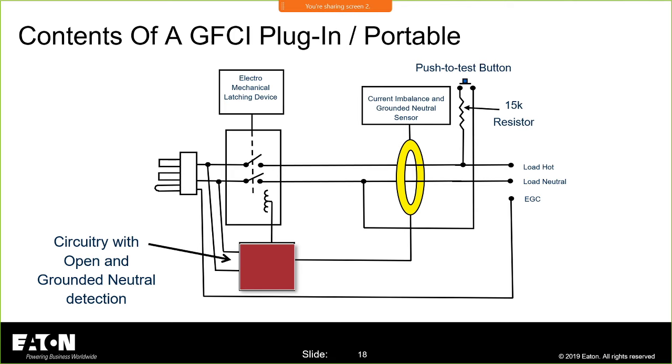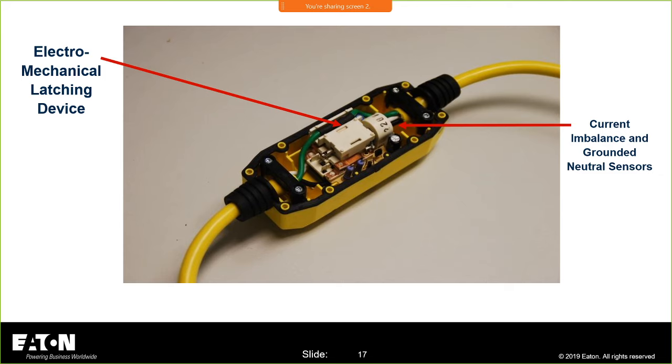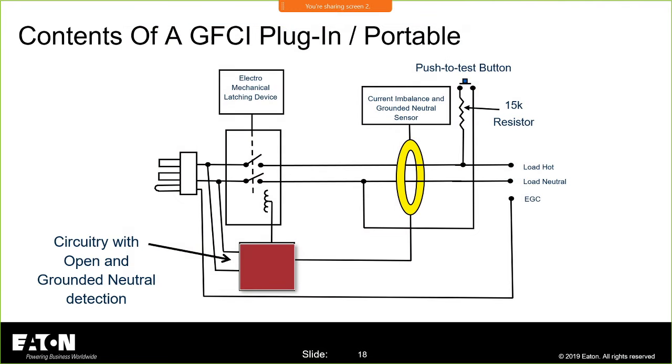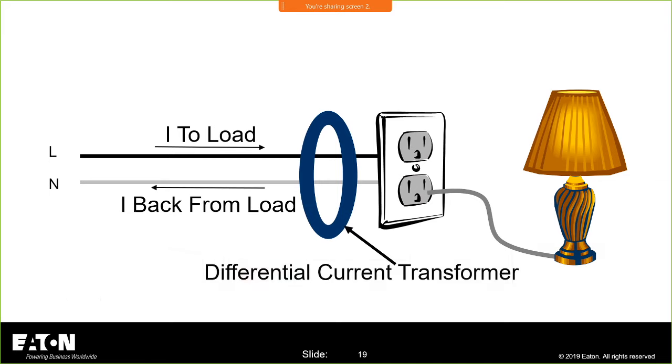So, all of these should be tested. I would say always test the GFCI before use, regardless of whether you're testing it once a month. You should always test a GFCI before you use it. You've got to plug into something. If you have this product in your hand, you're carrying it out to a job site, plug it in, turn it on, test it, and reset it. It takes a couple seconds. It's not very difficult. So please test before use.